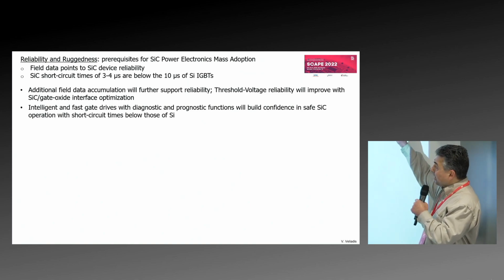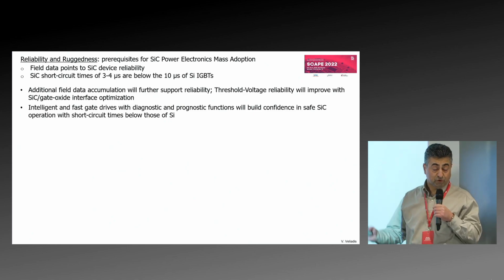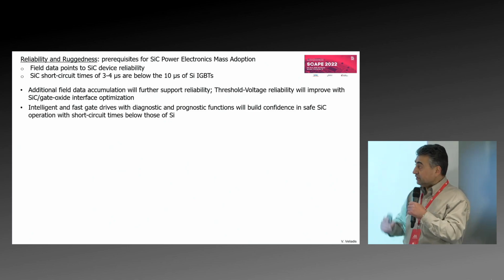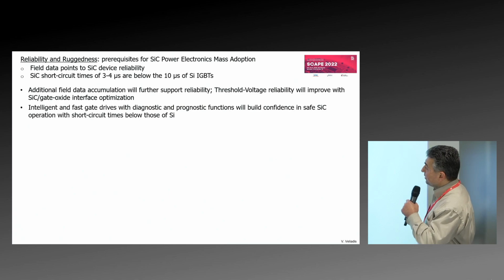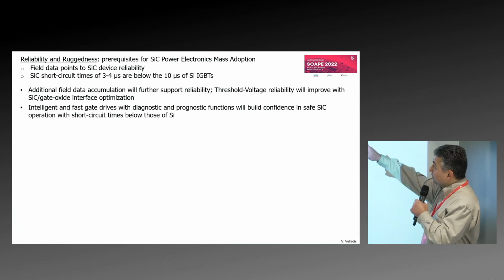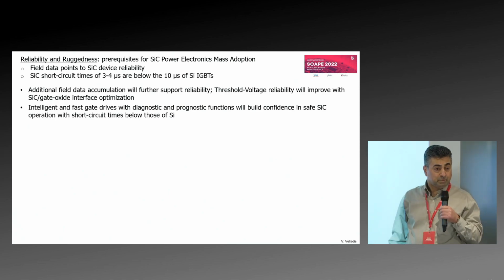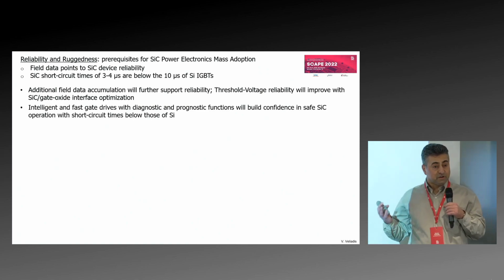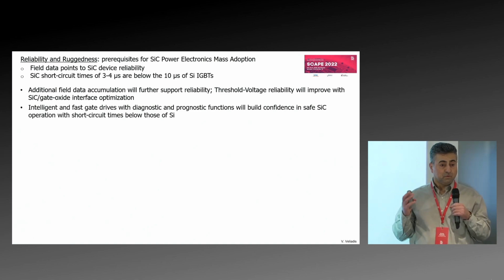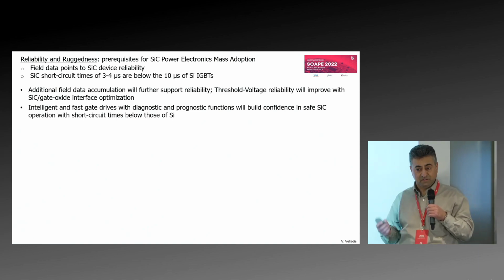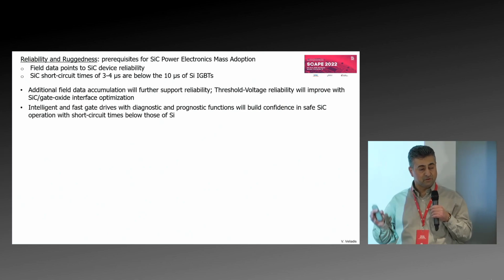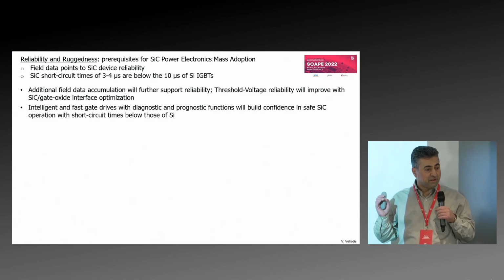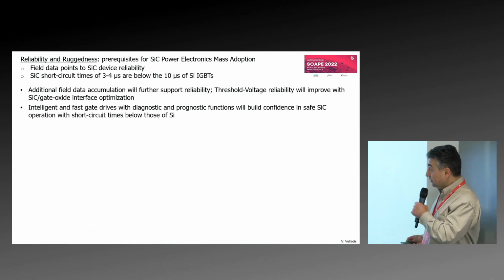So the improvements that will happen in the gate oxide will take care of this threshold voltage instability, which is one of the last reliability items. And of course, the 3 to 4 microseconds of short circuit time versus 10 that a lot of power electronics engineers worry about, that will be taken care of with the fast, intelligent drives that have prognostic, diagnostic functions, so they will be able to give you that safe operating area you're used to dealing with in silicon.